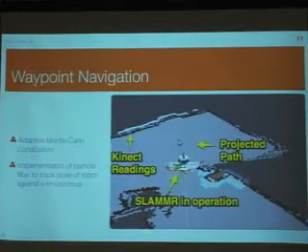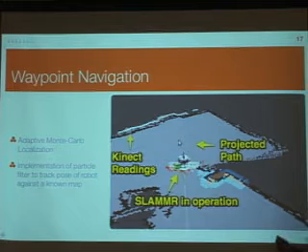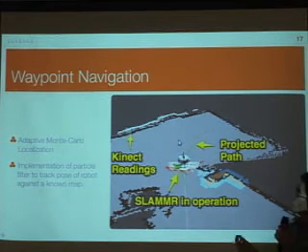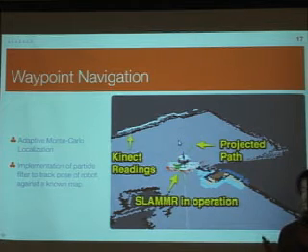And because we're achieving waypoint navigation in our project goal, we will need a more accurate grid map of the room. So that's why we use the first SLAM, which is the scan stitching one, to accomplish the waypoint navigation. We're using adaptive Monte Carlo localization, which is essentially just a particle filter, to estimate where the robot is.